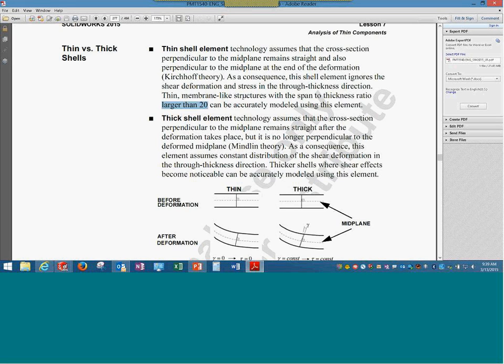As said yesterday, for any shell element that you are creating, it is fine to use thick elements because obviously you are considering all the things. And obviously, when you use thick elements, they take a little bit more time to solve than thin elements. Whereas, ensure you are selecting only the right geometries for thin elements. If you make a mistake in replacing geometries with thin, then obviously it messes it up.